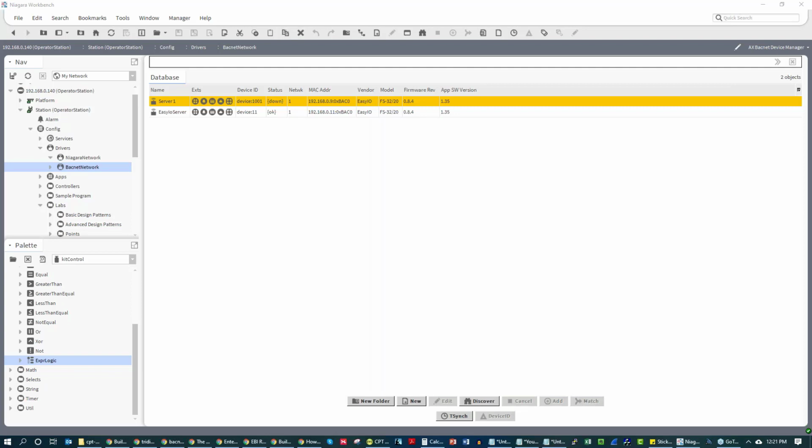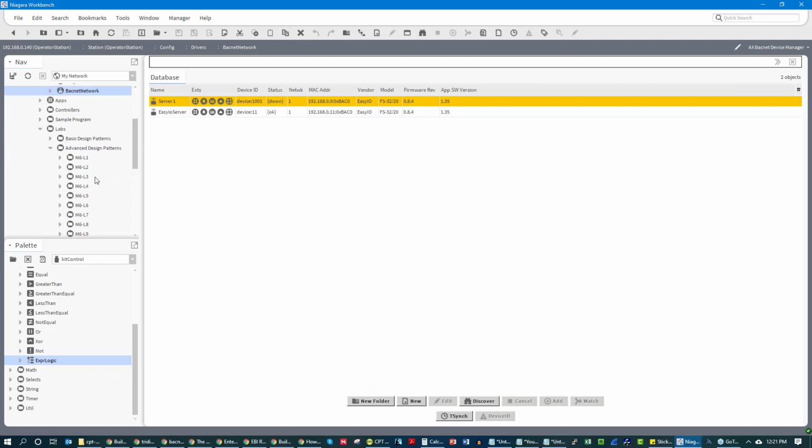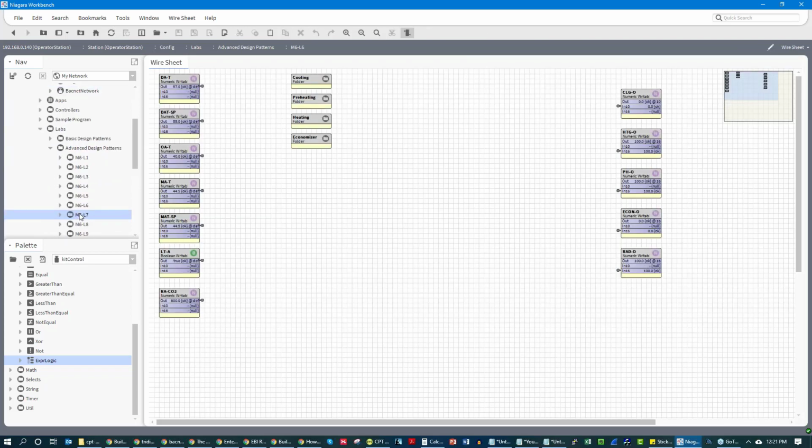So I see Mirza, I think I said that right. You can use subroutine DDC to make your DDC more efficient. You should program a subroutine anytime a calculation or control sequence needs to be implemented repeatedly. For instance, you need to convert FPM to CFM for a number of VAV boxes. Yeah, exactly. What you should not do is do this, where you go and, let me show you.